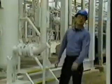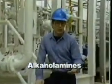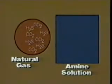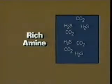The most common process for gas sweetening uses substances known as alkanol amines, more commonly referred to as amines. An amine solution is mainly water, with only 10 to 50% of the solution being amine. Amine solutions absorb acid gases from natural gas, like a sponge. Now, it depends on the concentration of the amine solution, but typically, 1 gallon of amine solution can absorb 3 to 5 cubic feet of acid gas. Before the amine solution absorbs acid gases, the amine solution is referred to as lean amine. After the amine solution absorbs acid gases, it's referred to as rich amine.